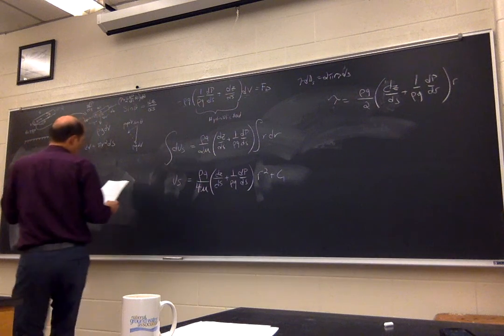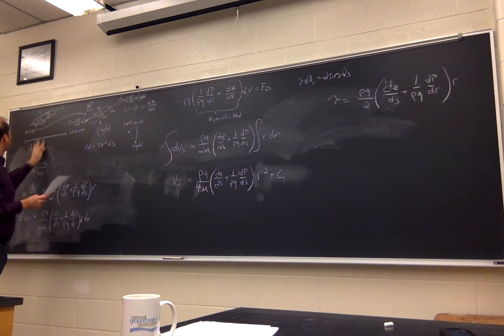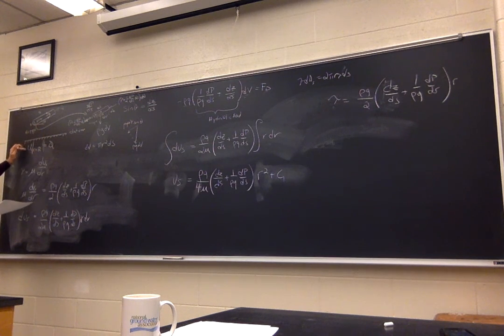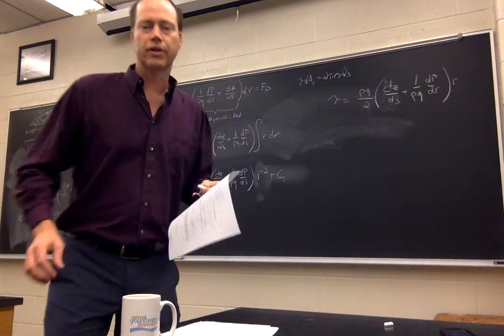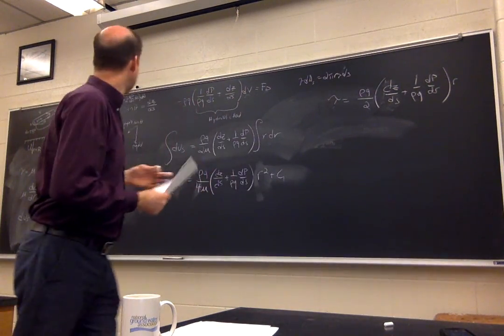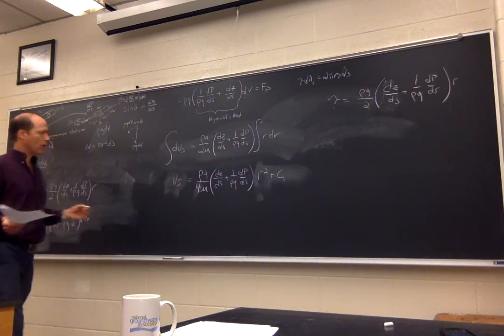And so the way to write that boundary condition is that the velocity in the s direction at little r equals big R is equal to 0. So the velocity in the s direction at the little r that I'm considering in my control volume scaled up to the total volume of the pipe is equal to 0. So we go in and we place that in.